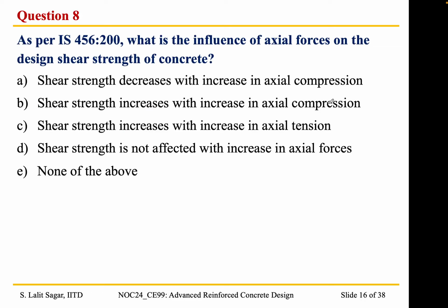So as per IS 456, what is the influence of axial forces on the design shear strength of concrete? Option D. Okay, thanks for the response. We can look at the answer now. So the correct answer is, in fact, option B, because when the axial compression within a beam increases, that leads to enhanced shear strength.